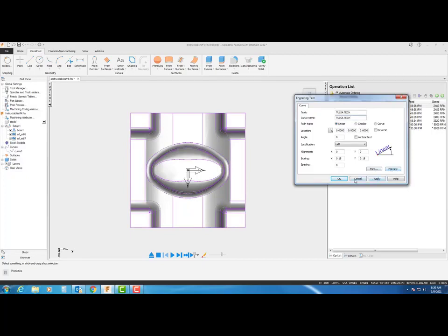I don't want to hit apply or OK. I simply want to hit preview first to see what it's going to look like. Now by default, this will come up as 1 inch. With that saying 1 inch and I hit preview, it's going to come up pretty big. So from here, it will take quite a bit of playing around to get it where you want it. I'll make it quick because I've already done this once. So I'm going to make this 150 thousandths tall, 150 thousandths wide, and then I'm going to hit preview. That looks a lot more manageable.